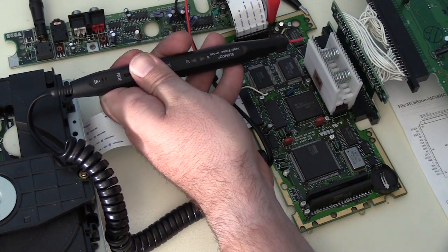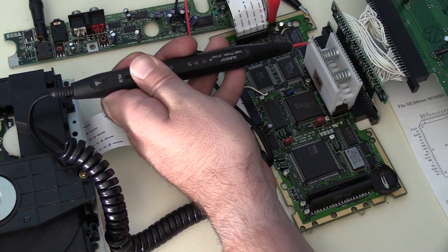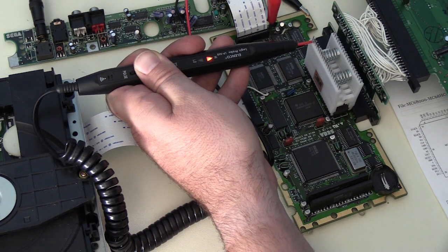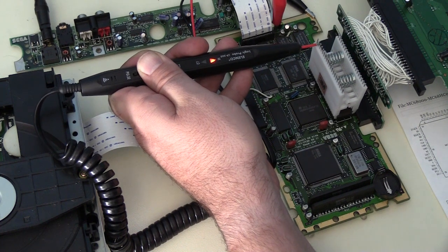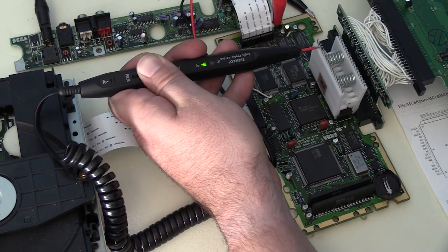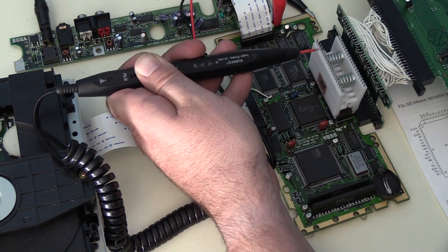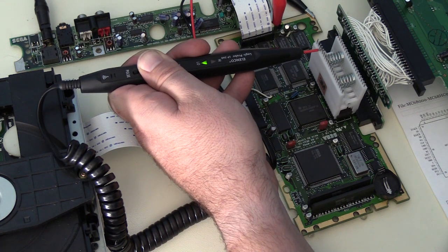And first pin is our power lead, so that's going to always hold high. Second one is chip enable. That would normally be flickering to show activity, but the Sega CD system is pretty much hung at this point, so that's holding high. Then that's data line 15, it's just held low. And we're going to see the same thing for all the other data lines.